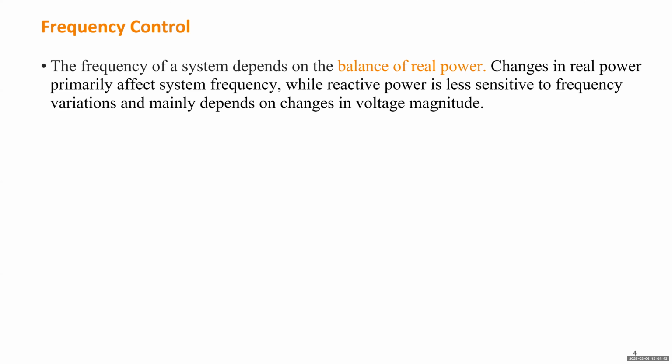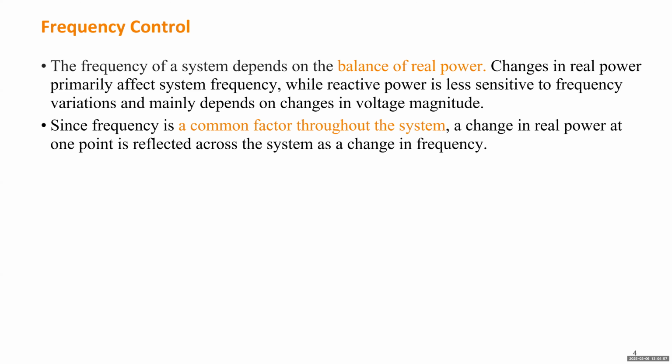Okay, because by changing the frequency, you will change the active power. By regulating active power, you are going to change the frequency. So here we don't differentiate the frequency control from the active power control. Similarly, later in the voltage control section, we'll cover both the voltage controller and the reactive power controller in the same session.